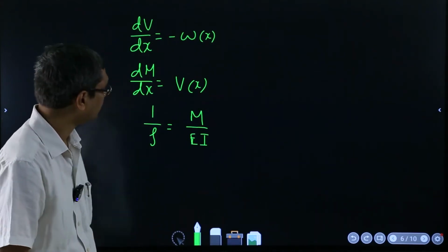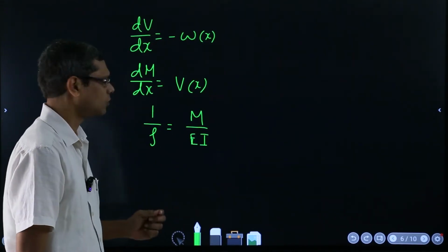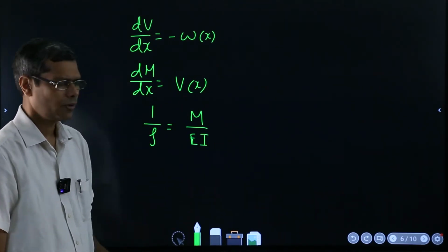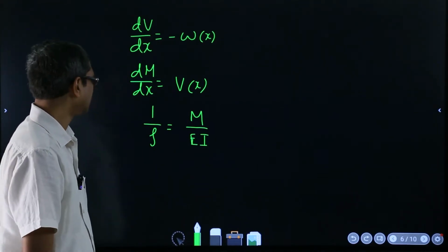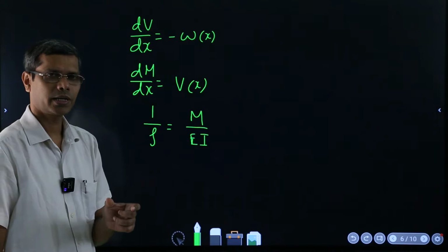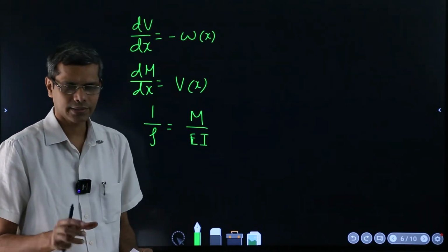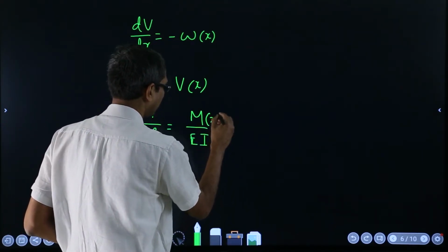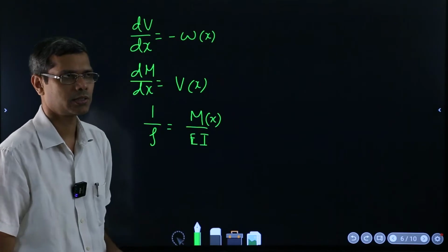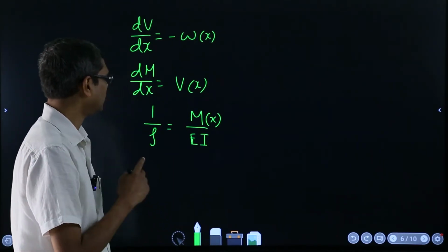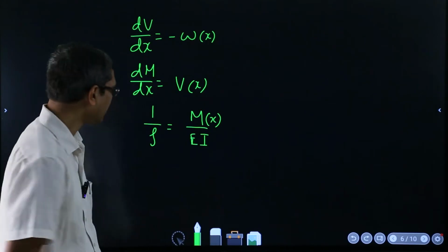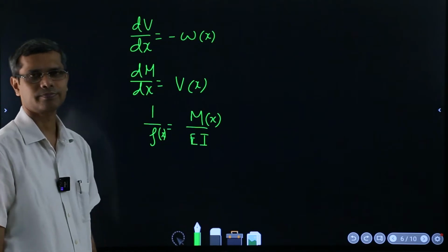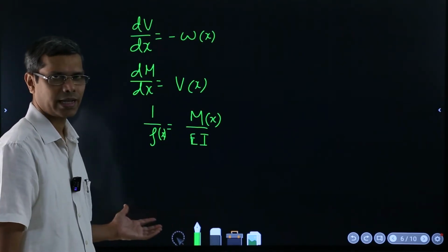But then we discussed that in a condition where shearing force also exists, where it is not a case of pure bending, still segment by segment we can think of that segment as having a moment of the value at that location, M of x applied, and then you can also think that rho is also a function of x. So that is the basic idea.